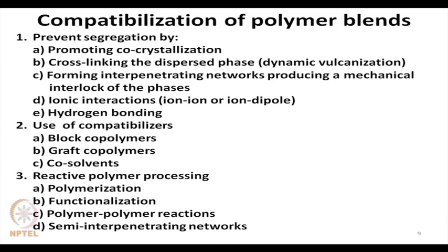If it is required that the polymer molecules are to be crystallized in the product, that means molecularly aligned to develop long range order, then the cooling rate is properly adjusted so that polymer molecules crystallize. So, that is a phenomenon of crystallization during cooling of the product within the mold.